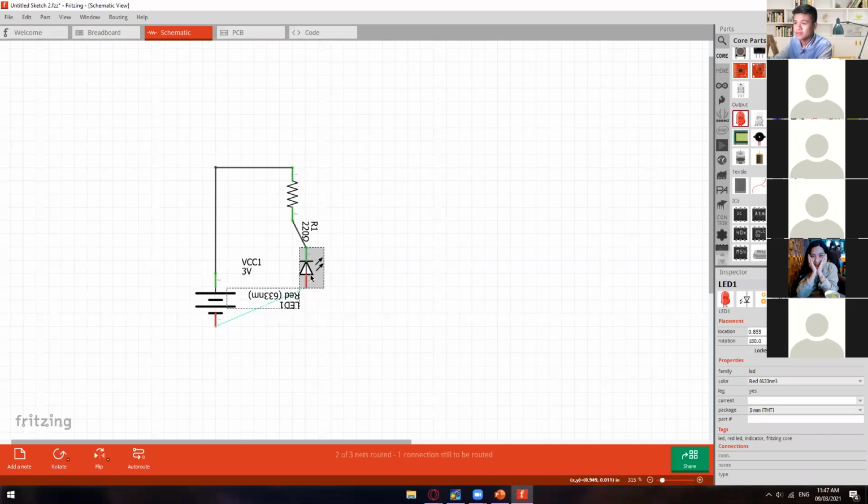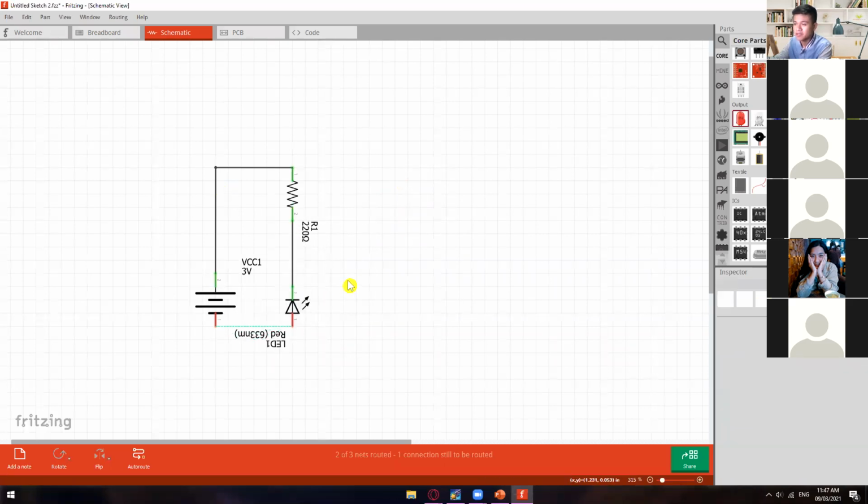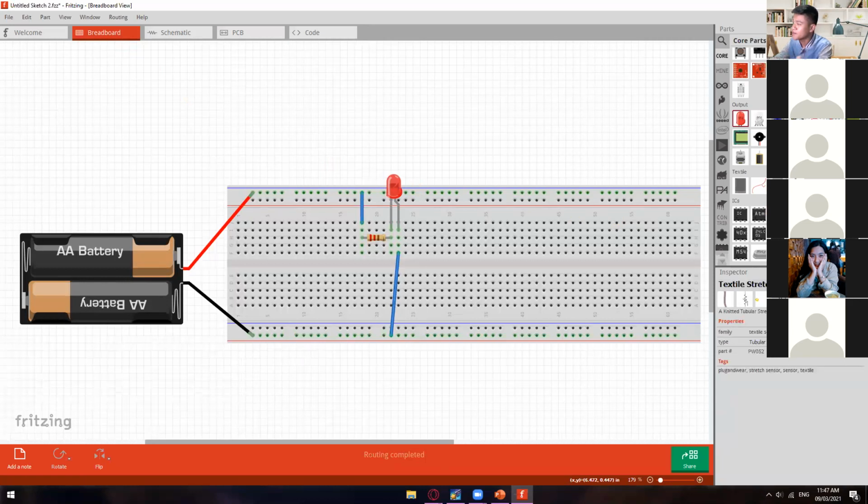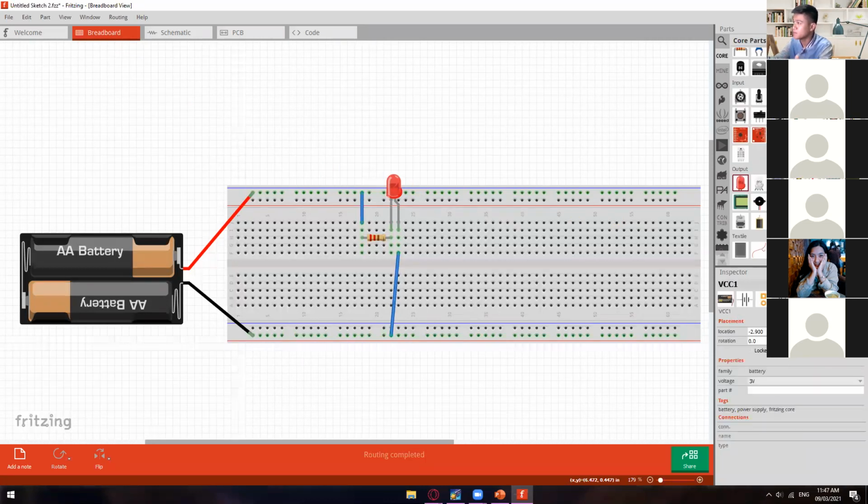So I guess when it comes to checking whether the connection is correct or not, it depends on your schematic. Most of our components have a polarity wherein positive should be connected to positive and negative should be connected to negative. Like polarized capacitors, or maybe potentiometers, because they have certain pins. So in that case, you really have to look for the data sheet of that component.